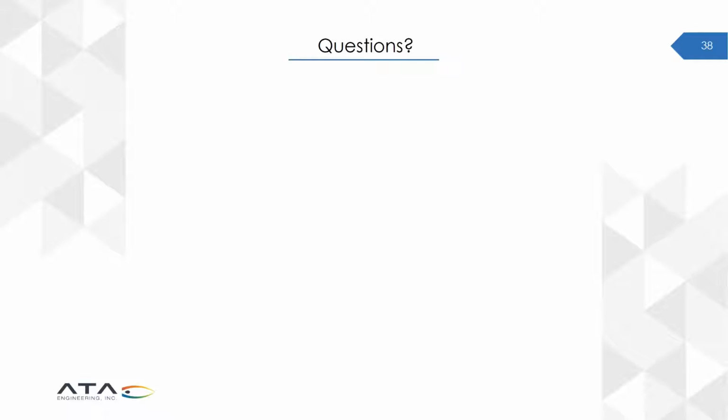Before we go, Christoph, to answer your question in the chat, the initial conditions, I did not. So the initial conditions you saw were updated in the script there. The initial condition for the background is just still air. Because it's a DFBI simulation, the initial conditions for the velocity is updated in the DFBI setting.